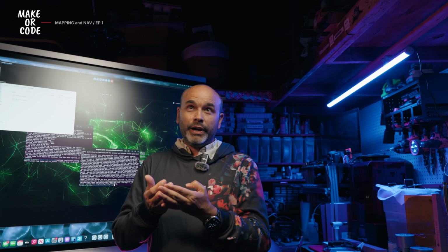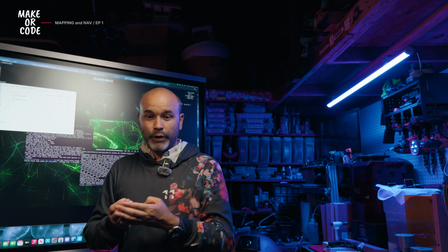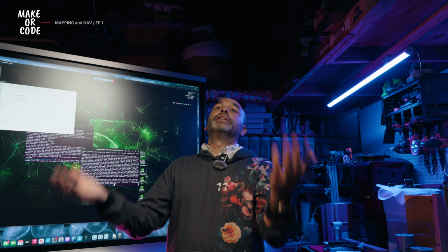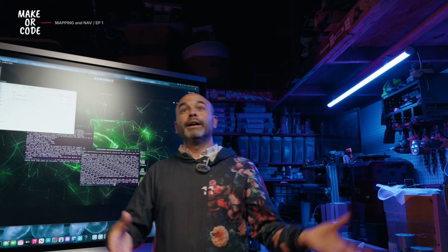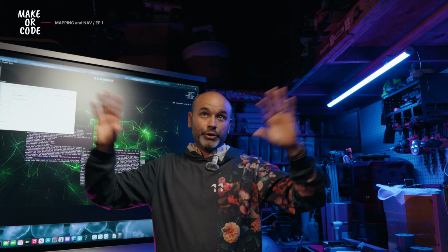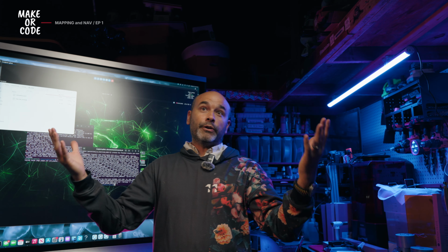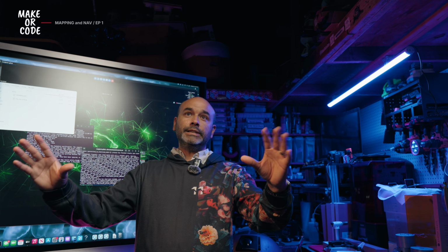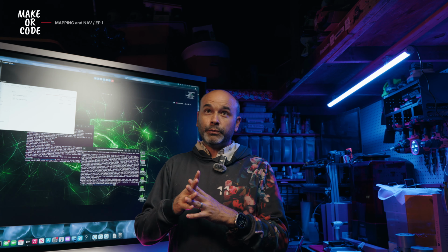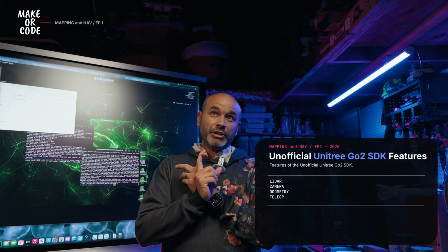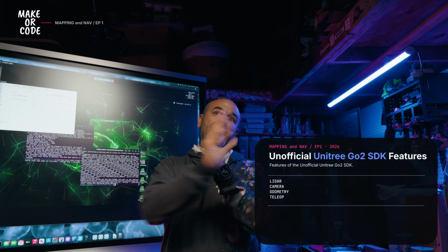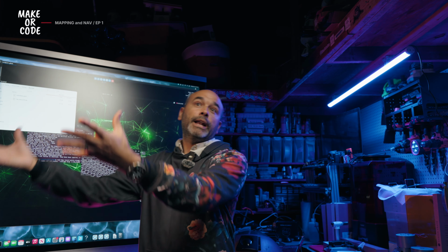So same way that you use the controls on your phone, that is streamed through the network. This captures that information through the network, passes it into a ROS2 environment, then it starts outputting ROS2 topics, just like a ROS2 environment. All wirelessly, no modifications required on the Go2, but this will allow me to now have LiDAR information, camera information, odometry information, teleop, all set up already.